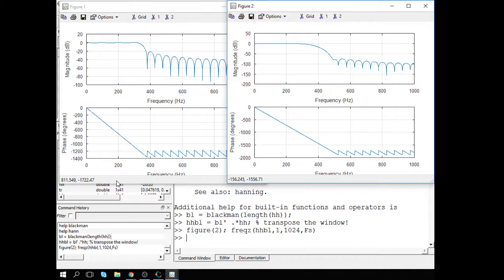So first, the cutoff frequency is simply plugged into the sinc function, along with the scaling factor to make it unity gain. Then we take a smoother window shape to reduce the effect of these high-frequency edges, which gets you better stop band attenuation at the cost of wider transition bandwidth.